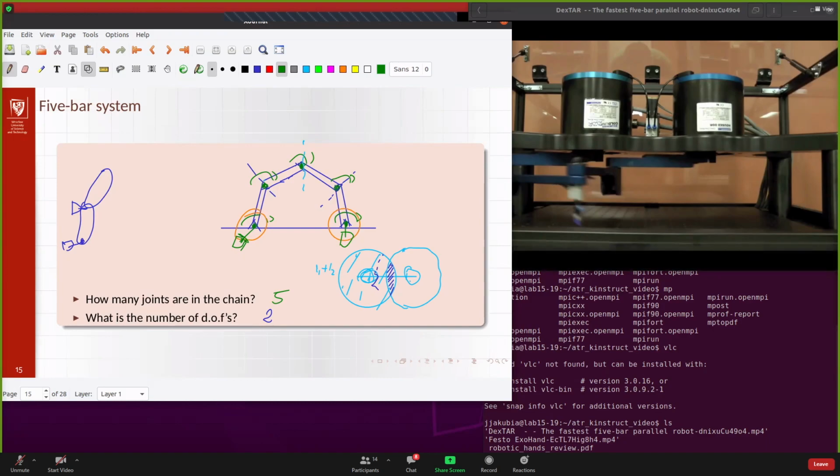If we don't have the mass on the moving arm, the moment of inertia is smaller. So using the same force, we can have a higher acceleration, or using the same acceleration, we need to apply a smaller moment, smaller torque in the motor to get the same effect. So smaller mass, and because of that, either smaller torque or higher acceleration, depending on in which direction we optimize. What about the precision?